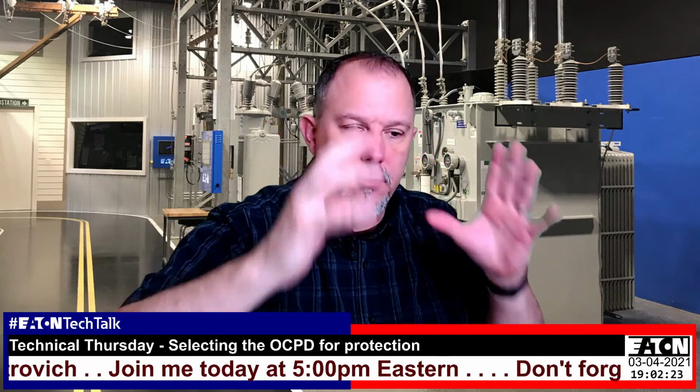Just based upon what we just said, if I have equipment with zone selective interlocking, I don't have a complete protection for the electrical worker. That, in itself, inside that equipment, does not lower the incident energy for the electrical worker.